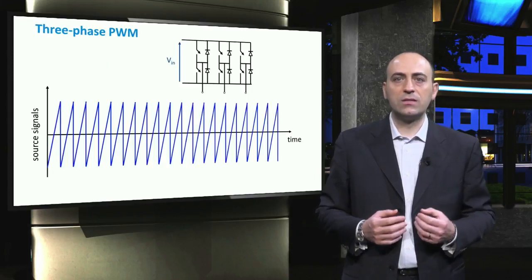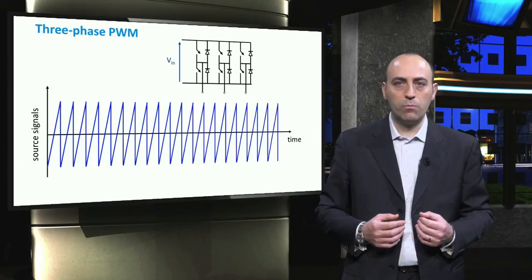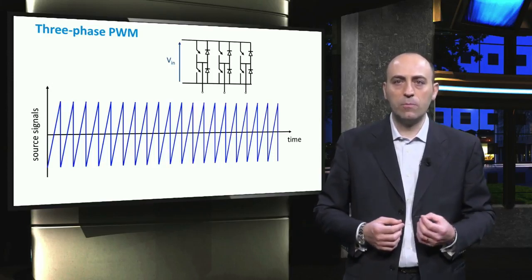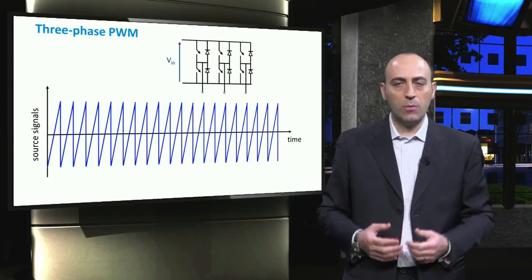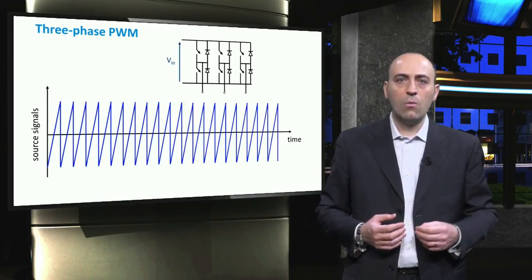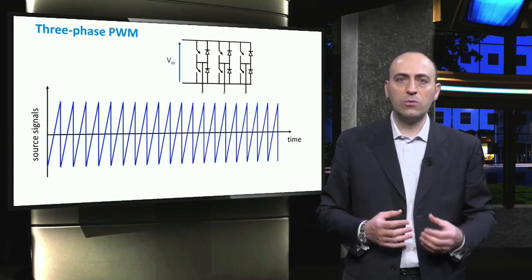In applications such as uninterruptible AC power supplies and AC motor drives, three-phase inverters are commonly used to supply three-phase loads. It is possible to supply a three-phase load by means of three separate single-phase inverters, where each inverter produces an output displaced by 120 degrees. Similar to the single-phase inverters, the objective in pulse-width modulated three-phase inverters is to shape and control the three-phase output voltages in magnitude and frequency with an essentially constant input voltage.